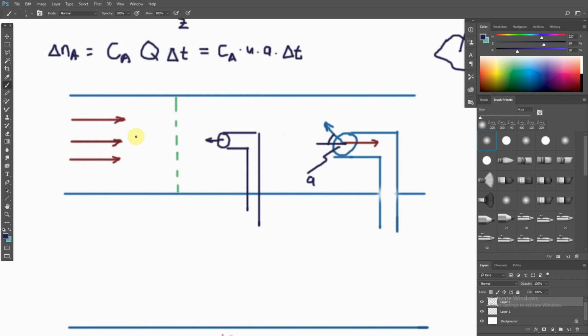And we can even imagine a situation like this. Let's say the hole was actually in this orientation. Then we can imagine that there's much less flow through this system and there's no direct flow into here. Of course, we know that doesn't really happen due to viscosity and pressure difference. However, just in terms of the direct fluid flow, there's no transfer of fluid across this space, because now your unit normal outward vector is normal to the fluid flow. It's at 90 degrees. It's perpendicular to the fluid flow.